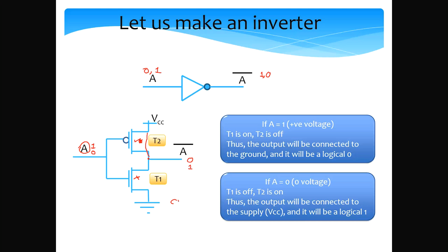So it's called a CMOS circuit, and so it's a combined circuit, right? It has both NMOS elements and PMOS elements. But the important thing is that we put NMOS and PMOS in series, and one end of NMOS is at the ground and one is at VCC.